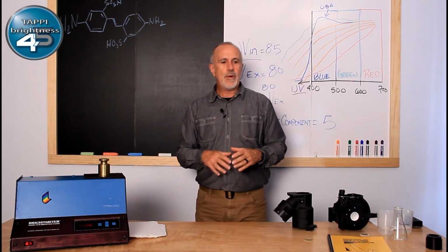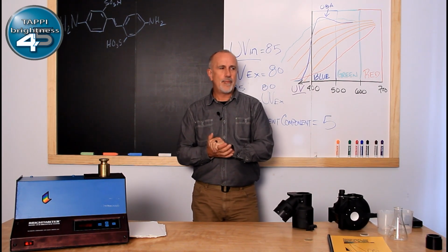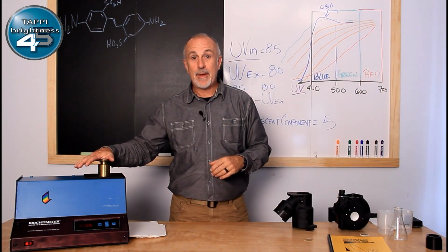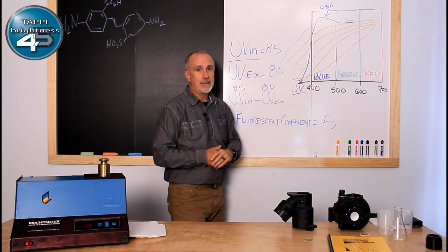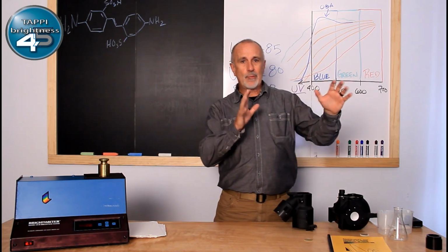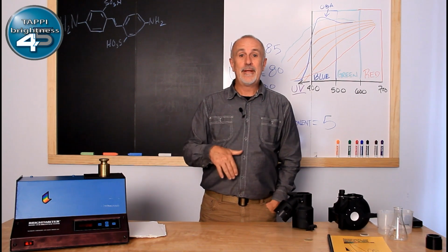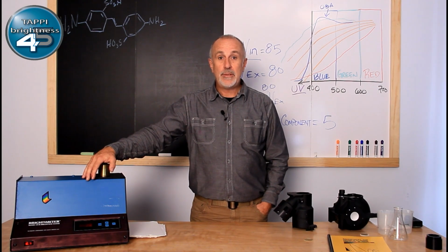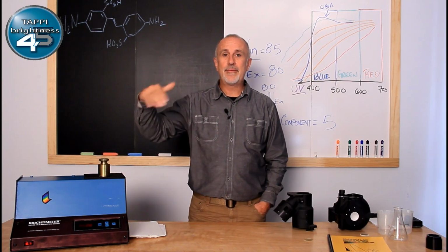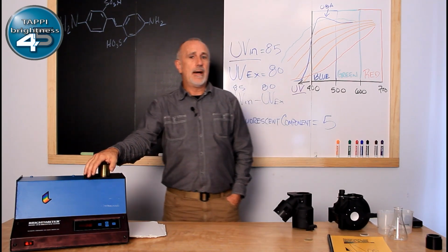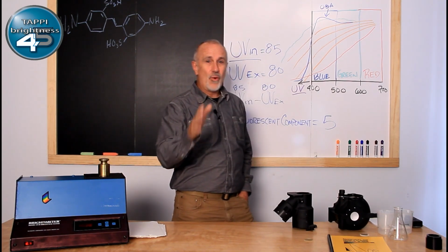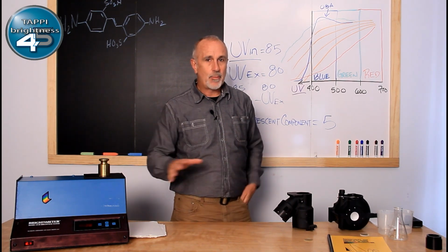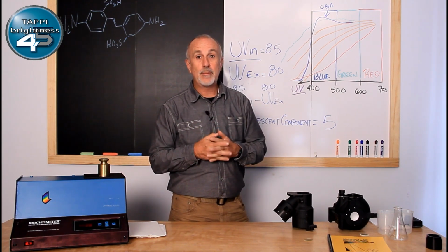What's interesting with that though is that back in the 1930s, when they were developing the original TAPPI method, and remember that was to look at this bleaching cycle, they really weren't thinking about the future of the chemistry that was going to come into the industry and how optical brighteners would be used so prevalently like they are today to achieve brightness levels. Unfortunately though, because of the goal of trying to reward a blue-white to the paper, the optical brighteners just fit in perfectly with the bleaching cycle.